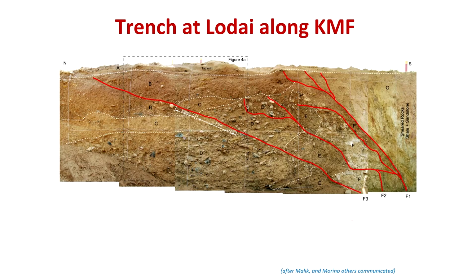And what I was emphasizing is that you need to identify each and every contact very precisely, and you need to measure the slip, and that net slip will help you. How you are going to calculate the net slip is very simple. If you have, for example, two layers here, and they are displaced along the fault here.